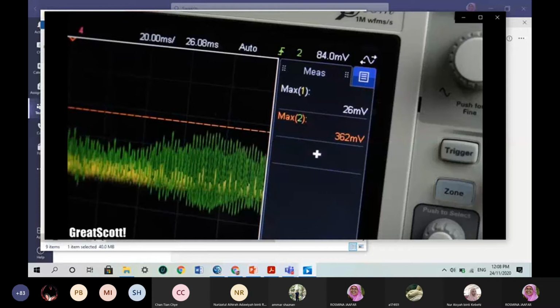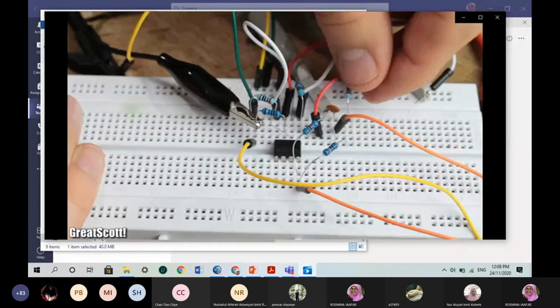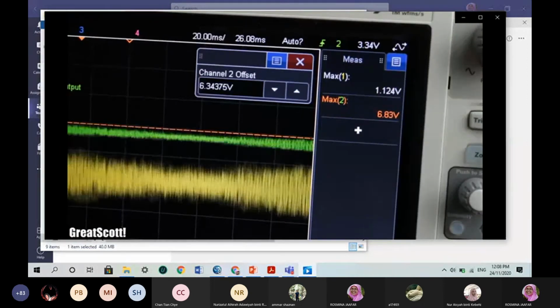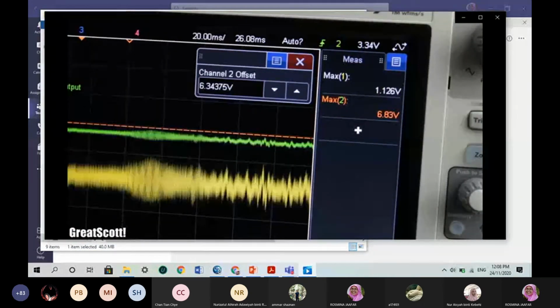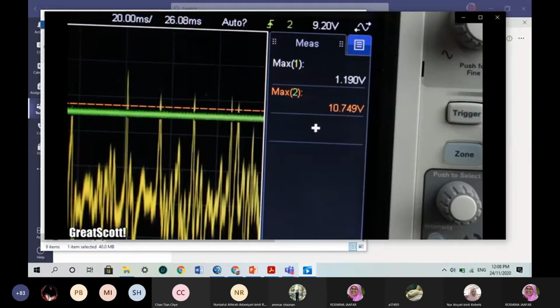But since that is normally not an option, we could also add a DC offset to the plus input. This way the complete amplification does work to some extent, but because we are amplifying a DC voltage as well this time, we hit the 10.8 volt output limit of the op-amp pretty quickly. Why 10.8 volts instead of the 12 volts of the supply voltage?